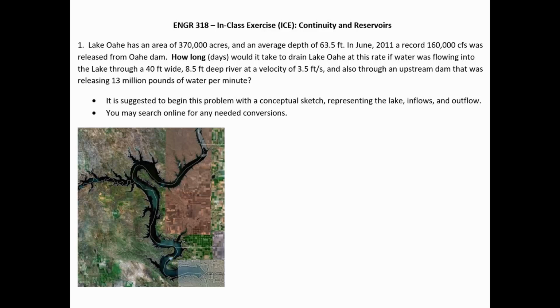And you can use your phone for the next, we have 12 minutes remaining approximately. There are some unit conversions in here that you may need to try and solve. For example, we have 13 million pounds of water per minute is coming from an upstream dam. And so you'll need to convert between million pounds to volumetric and so on.